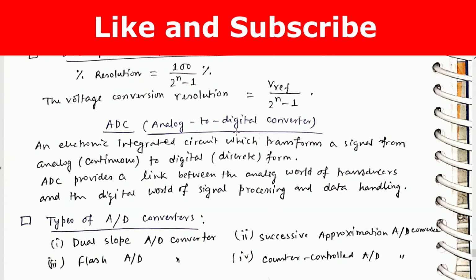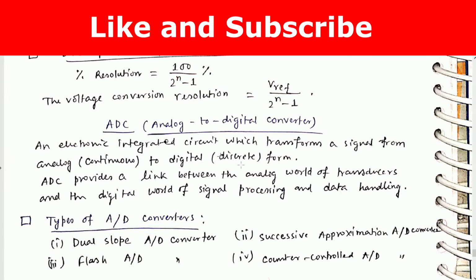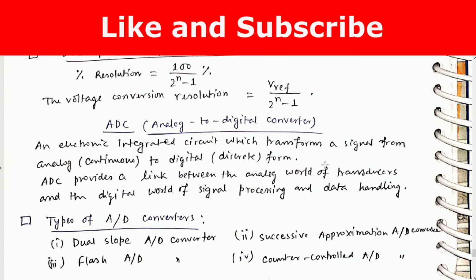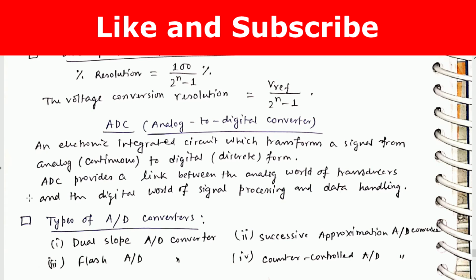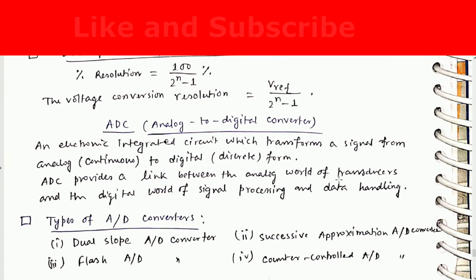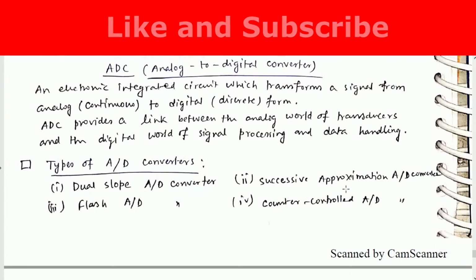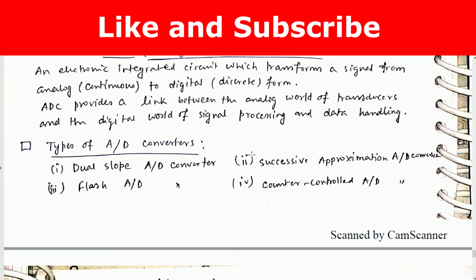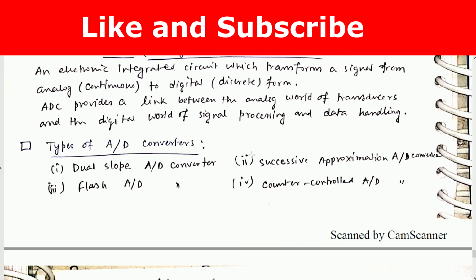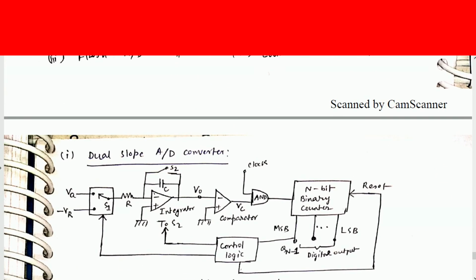Now let's talk about ADC, analog to digital converter. It is an electronic integrated circuit which transforms a signal from analog to digital. Analog means continuous, digital means discrete form. ADC provides a link between the analog world of transducers and the digital world of signal processing and data handling. Now four types of A by D converters are there: dual slope, flash AD, successive approximation AD, and counter controlled AD.